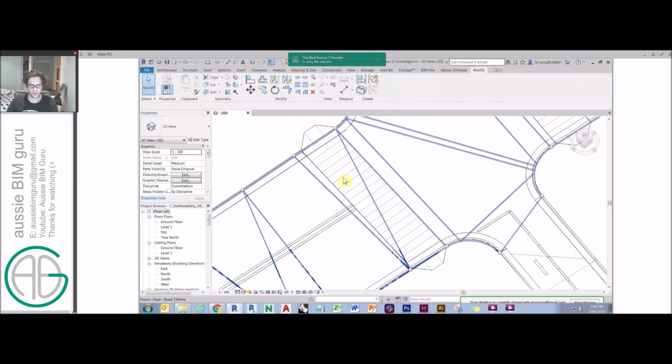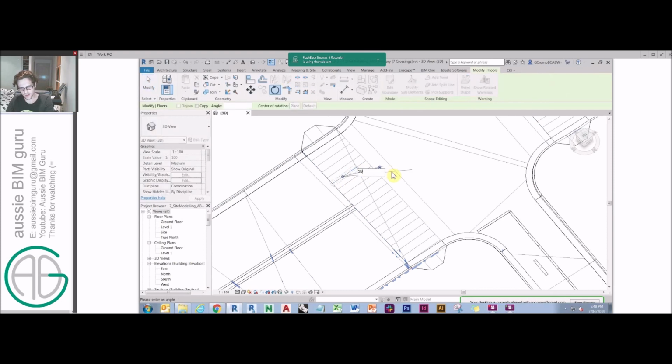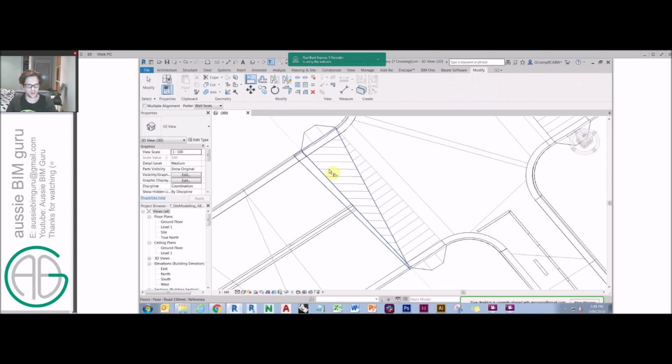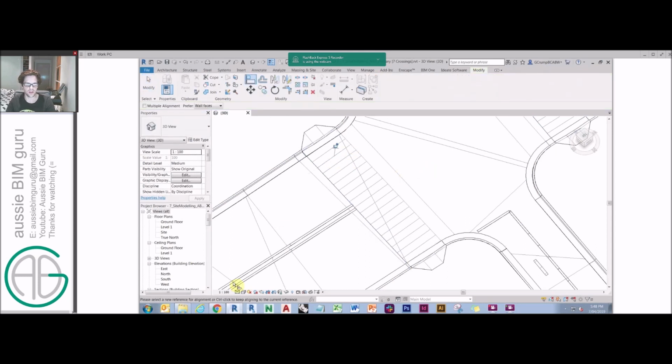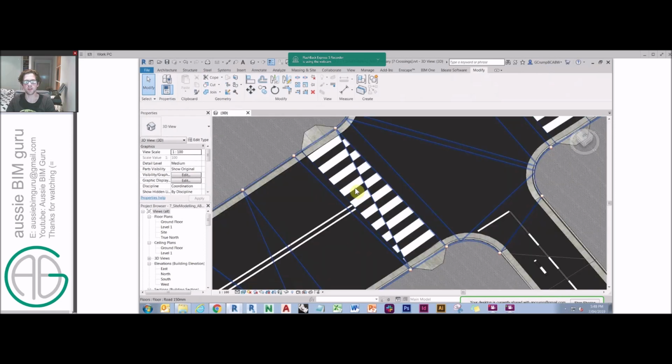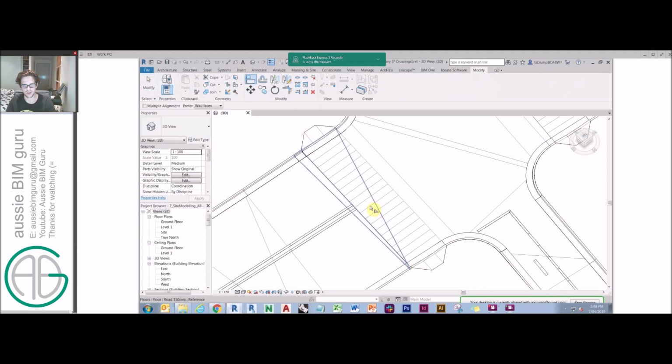From there, you may find that sometimes your pattern doesn't come in rotated properly by default. As long as you're in a 3D view, you can actually use the align tool on model patterns, even if they're on a very strange angle or a raking surface, and that's how you can line up your pattern so that when you go to realistic mode, your pattern will coincide with the direction you want it to face. Obviously the weakness there is the 600mm pattern could be the road or the stripe, which is simply just a matter of offsetting the pattern by one stripe in order for it to align.